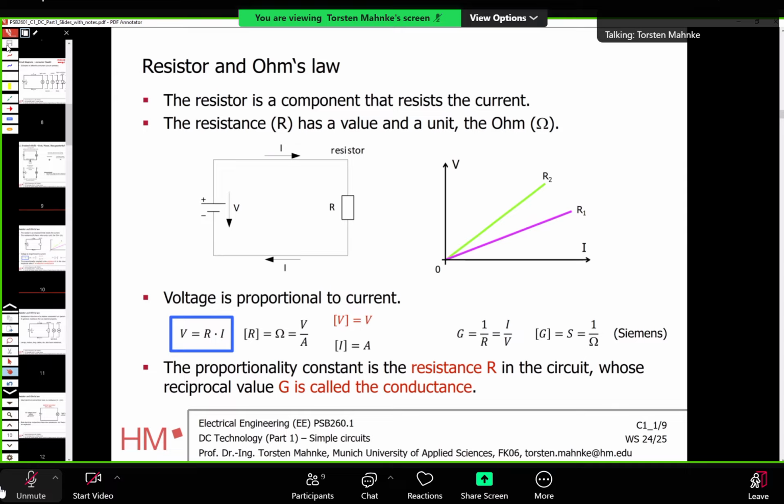Yeah. So if you have a battery and just a wire that loops around, doesn't that cause a problem? Because if you don't have a resistor on that wire, you technically have infinite conductance. Exactly, it is a problem. I don't know if everybody heard this at home. The question was, if you just have a battery and you connect the two poles with just a wire, is that a problem? Because there's no current limiting resistance in that circuit.